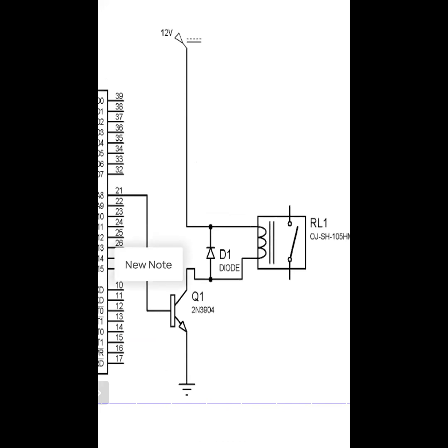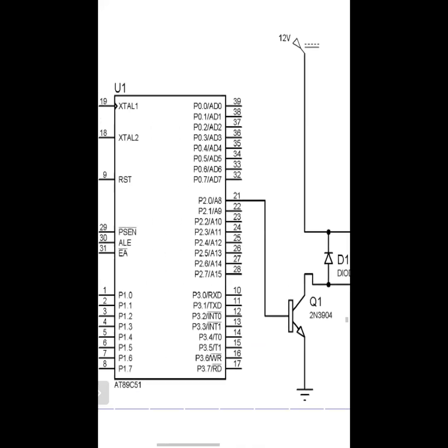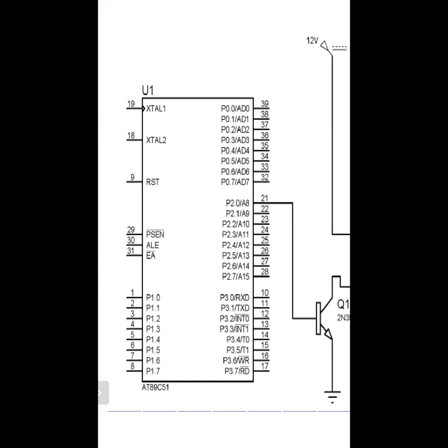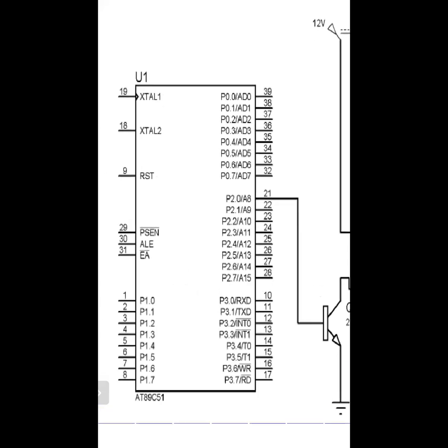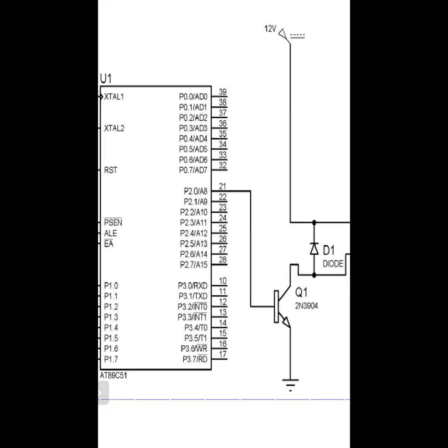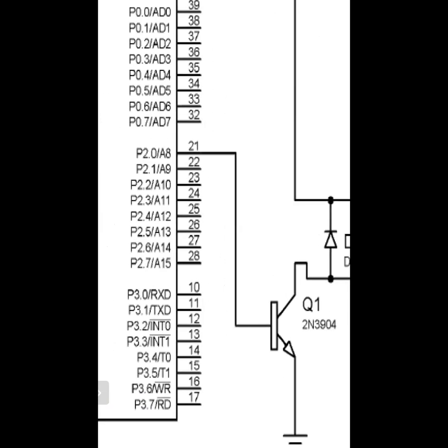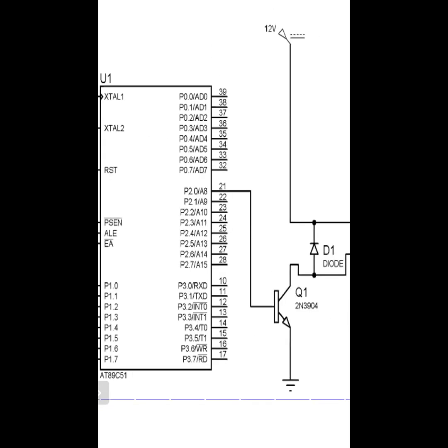See, one by one, what is the connection? This is our 8051 controller. You connect one pin here; I am connecting port number 2.0 to the transistor.